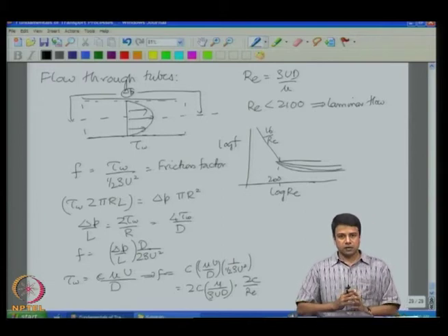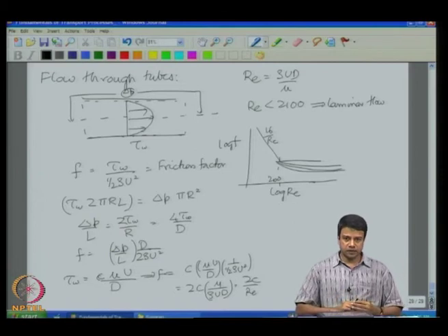Okay. In all cases, in heat, mass and momentum transfer, you are interested in predicting the average transport rate, which is an extensive quantity that depends on the system size, or the average flux, which is the transport of that quantity per unit area per unit time. And we can define non-dimensional fluxes by using the diffusion coefficient to non-dimensionalize the flux. Okay. And that gives me the Nusselt number, the Sherwood number. Okay. And these have to be a function of other dimensionless groups.